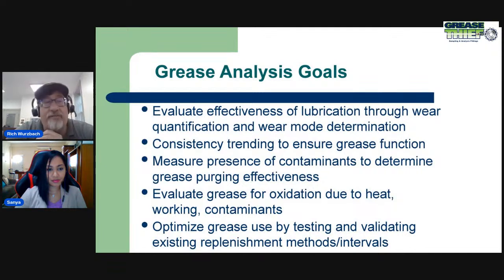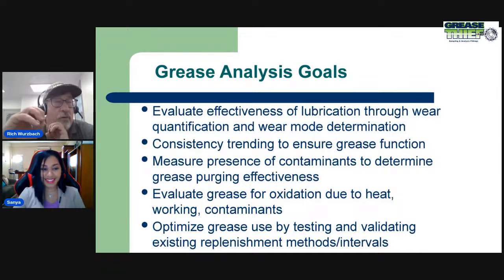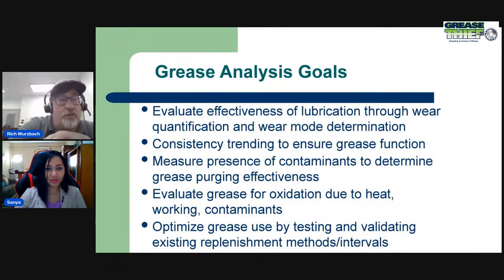Is it abrasive? Is it adhesive because of a lack of lubricating film? Is it a corrosive wear mechanism? What's really causing that? We can also trend the consistency to ensure that the grease is still going to do what it needs to do, which is flow, get to the location, stay there in contact with those parts, and then be displaced when the new grease comes in.